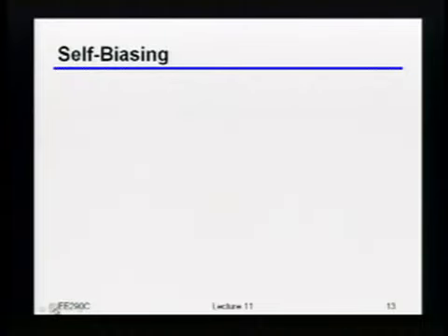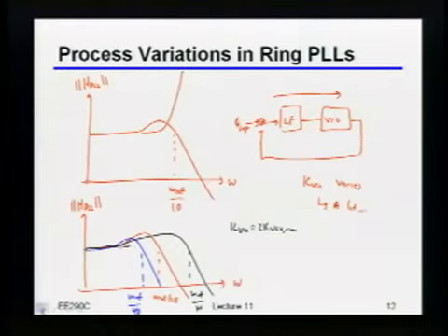I just got an additional question about this K for the digital VCO. I remember someone told me it's really not linear, right? Does that have any kind of implication? Yes and no. In this particular context of setting the loop bandwidth, I'm saying that the linearized KVCO could be moving. Now, what's true is that I may want to use this PLL with 10 different reference frequencies, or with 10 different output frequencies, right? Then it's even worse, because I have to put the bandwidth at whatever the worst possible thing that could ever happen to me would be. And by the way, I focused on KVCO, but this loop filter varies too, right? Charge pump actually varies too.